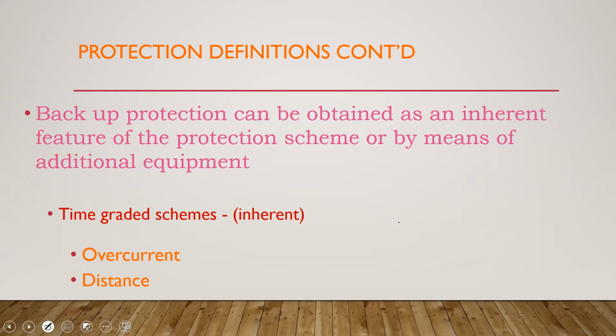Remember that firehouse example, where we said that all the systems will detect the fault and all will start operating, but if the primary protection operates, then the others will simply retreat and reset. That type of operation is obtained when we are dealing with overcurrent or distance schemes.